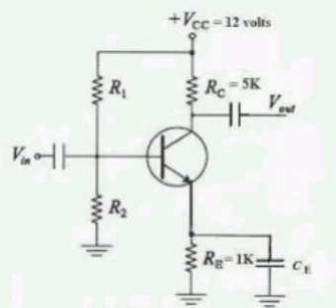Phi equal to cos inverse of 0.85. Phi equal to 31.788 degrees. Reactive power Q equal to Vrms into Irms sin phi. That equal to 240 into 416.67 into sin 31.788. That equal to 52682 VAR, that is 52.678 kilo VAR. S bar equal to P plus jQ. S bar equal to 85 plus j52.678 kilovolt amperes.